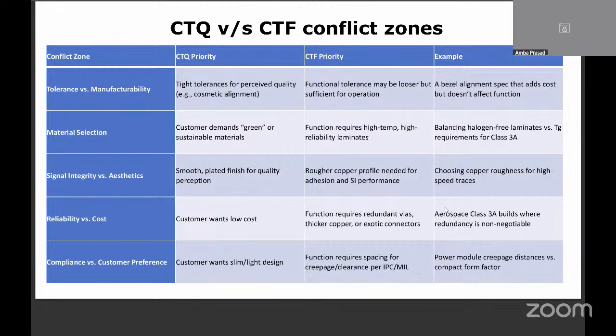Now, all the R&D is almost stopped in PCB material. Now a lot of R&D and effort is happening on copper finish, because when we say 144 Gbps, the skin depth is even less. Any defect on the copper surface, let's say it is higher than the skin depth, we are going to have problems. So that's how it is.